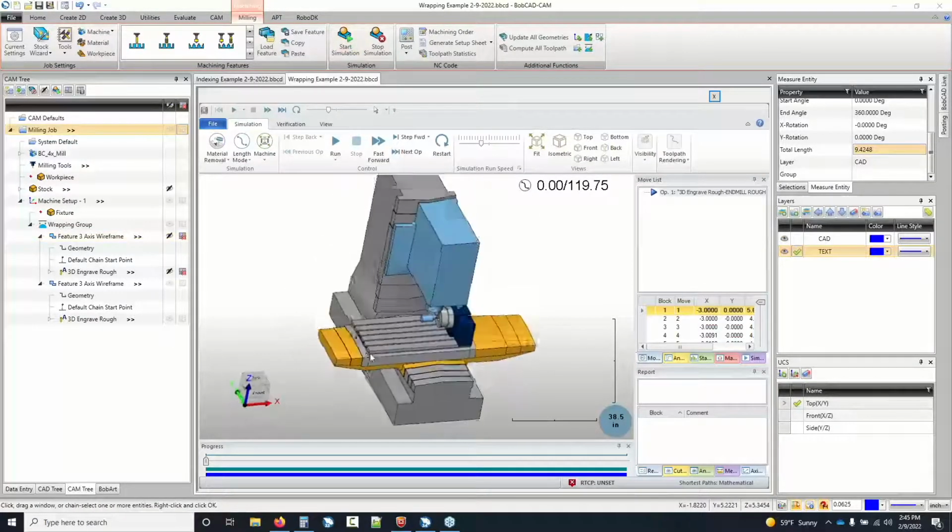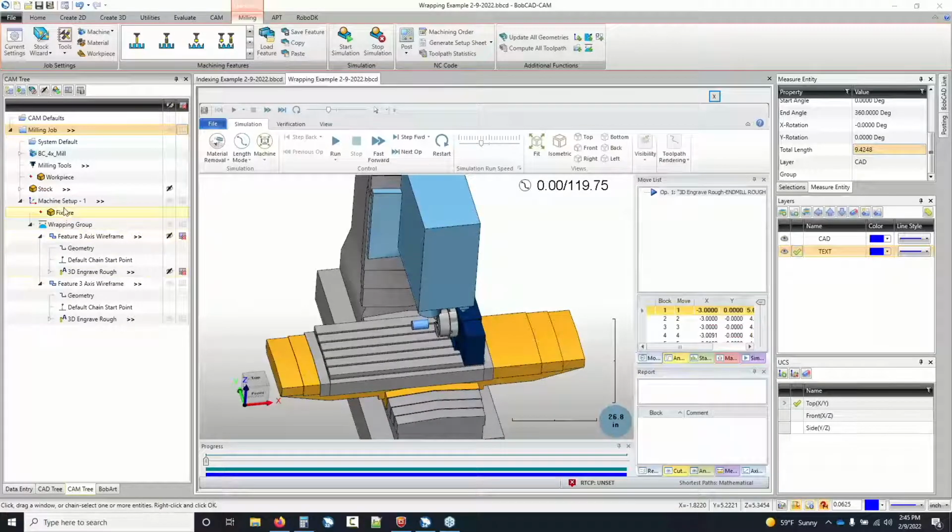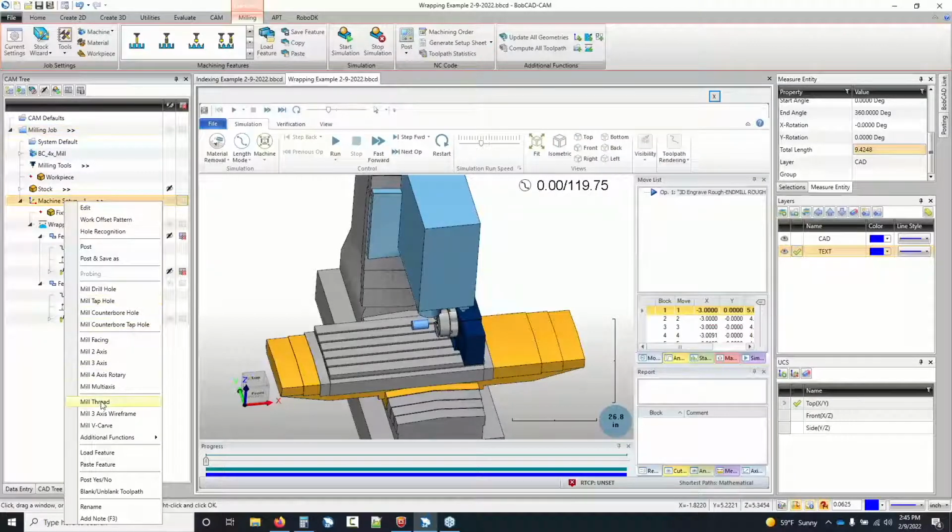And then right here, let's see. Is there another way to make a proper thread around a cylinder? You'd have to know the pitch and all that stuff, and know your settings for it. You could use, if it's around a 4-axis, nothing really defined. The mill thread is going to be like a 3-axis, 2-axis, whatever you want to call it, style there. Not really. You'd have to figure out your pitch and all that stuff.